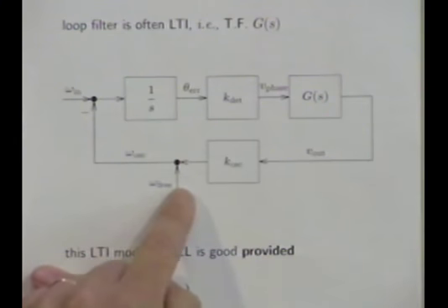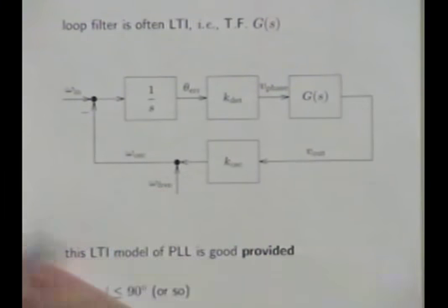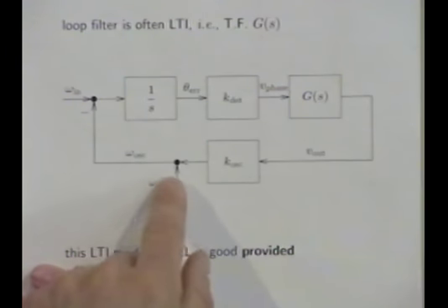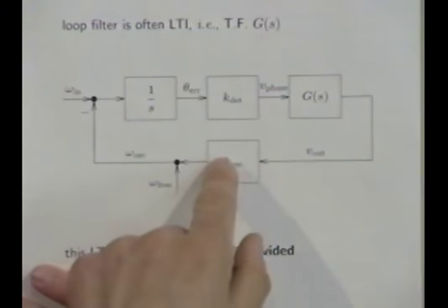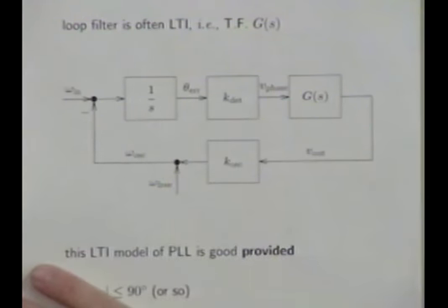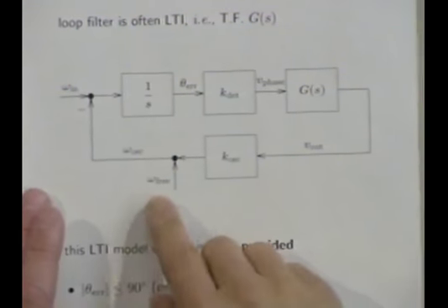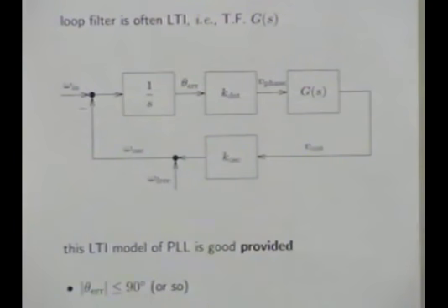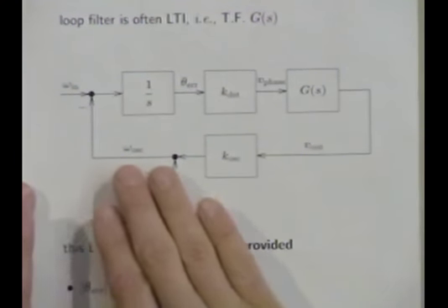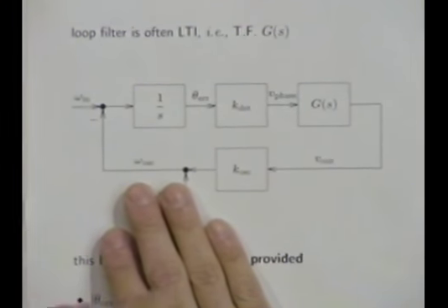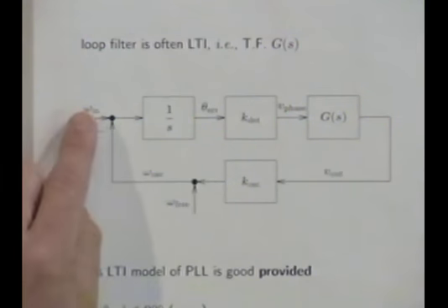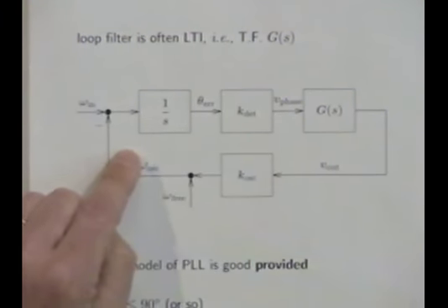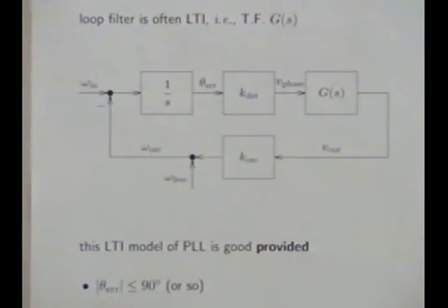That's kind of like integral action. And what that basically says is that no matter what the free running frequency is, this thing will tune this oscillator to lock to this thing. Okay? So at least in this analysis, omega free goes away. It's going to come back soon. Okay, now let's look at the transfer function from omega in to omega os. It'll be very interesting. Its DC gain is going to have a very important meaning.